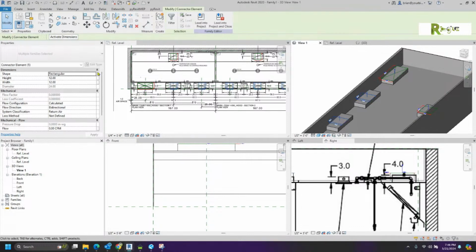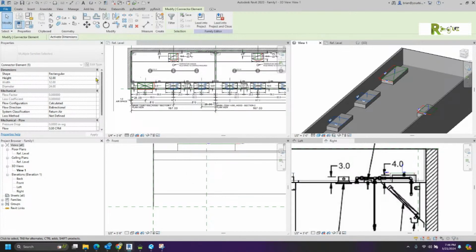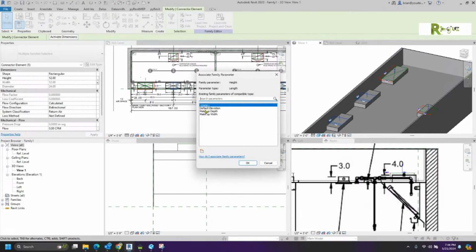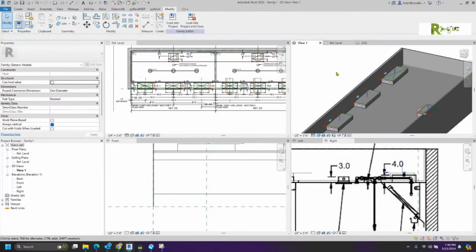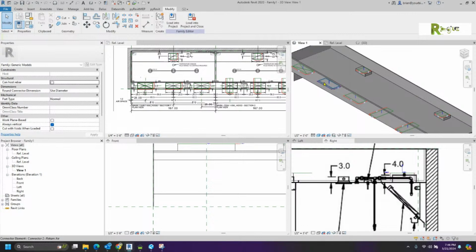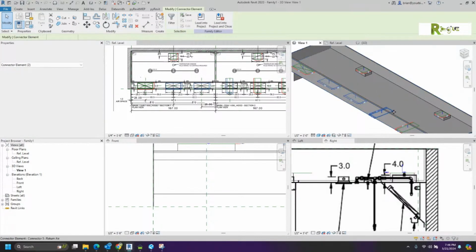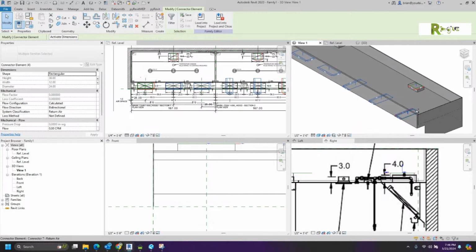And we said that this one here is the makeup air depth. And this one here is the makeup air width. And the whole thing that we just did is now. Oh, well, last thing I didn't fix, let me fix it real quick, is all of these have to be return air.